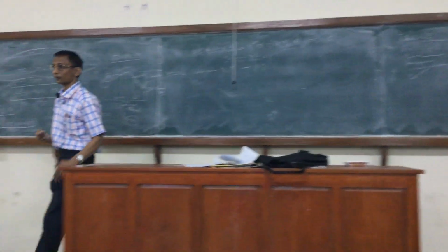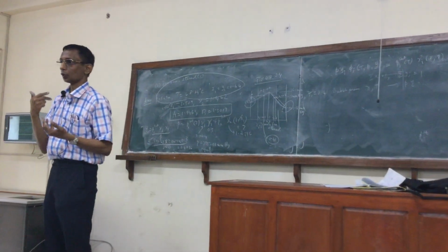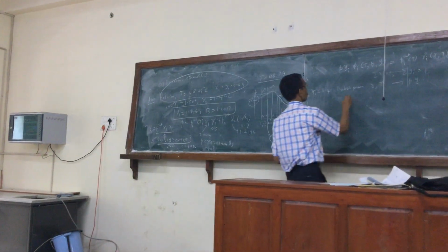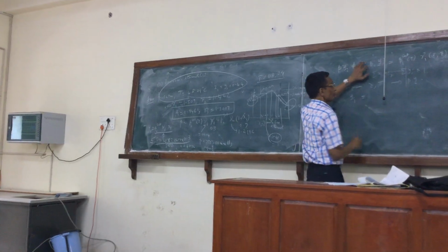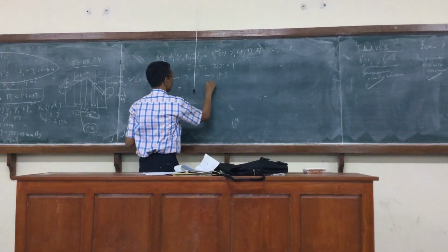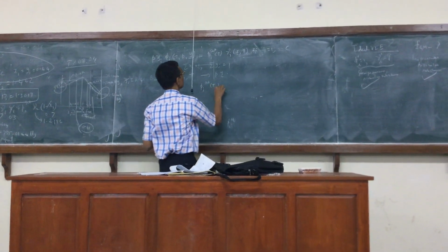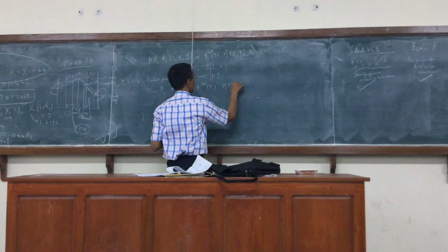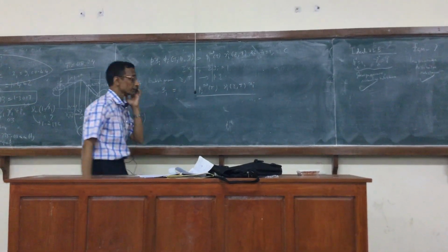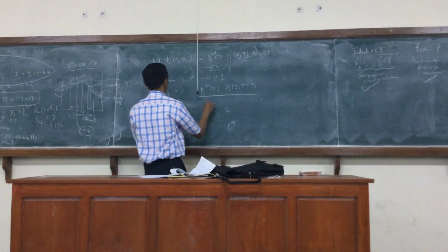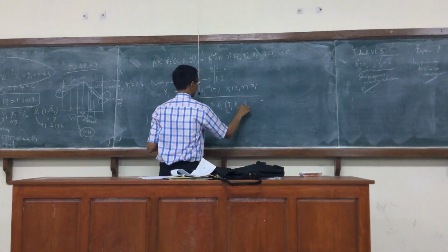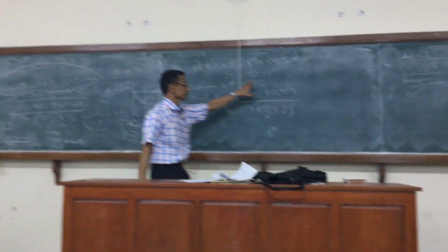The whole idea is first to write an expression for the y from the equation. So we wrote yi equal to Pi sat of T, gamma i of x, T, xi, divided by phi i of y, P, times P. Now I ask what is it that I don't know.